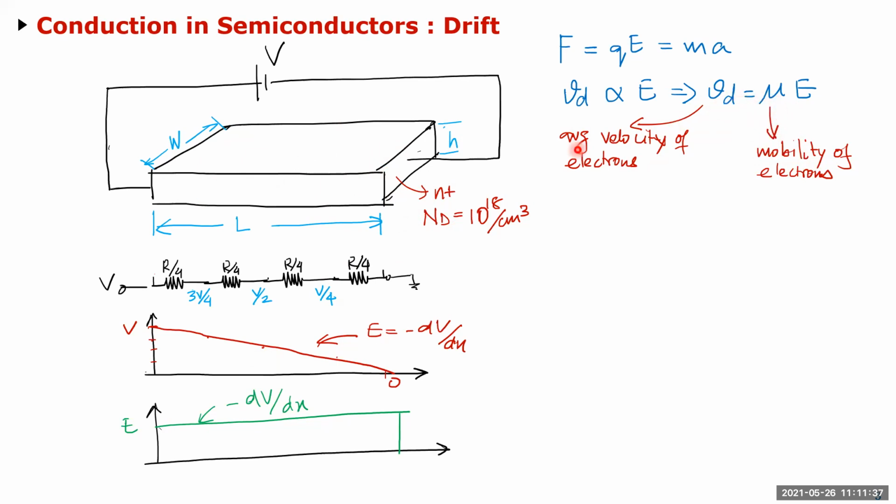So that average velocity of the electrons passing through a certain cross-section area is proportional to the applied electric field. When we look at short channels later on in the course, we'll see that as the electric field gets higher and higher, it's not proportional anymore. It saturates at a point, and that's the big difference. The equations we are deriving right now are what's called the long channel equations.